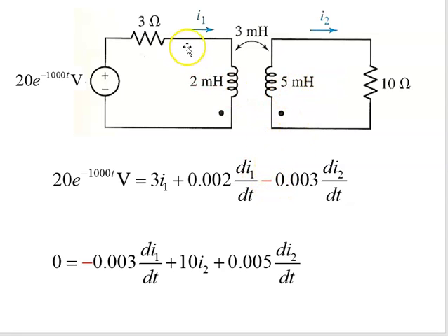The big key here: our self-induced voltage across the inductor, our mutually induced voltage across the inductor, since this dotted terminal is at the bottom, the mutually induced voltage is in this direction, right? So there's our VM, so we end up subtracting that.